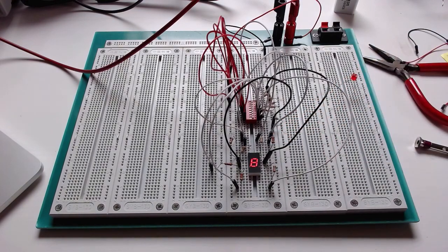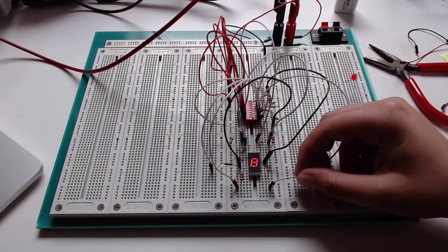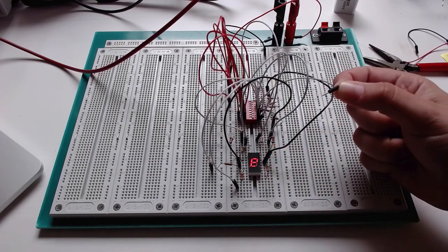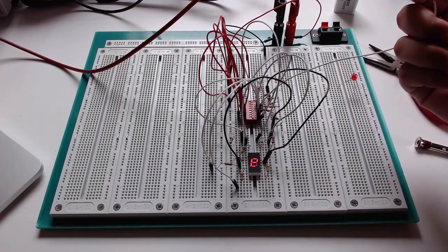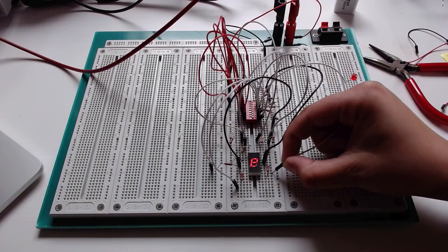This is the most commonly wired wrong thing that I see out of both digital systems and microcontroller students. Okay, so of all of the classes that I teach, of all of the subjects that I teach, the wiring of a 7-segment display is the single thing that I see done the most wrong. So I want to show you a couple of wrong things that students do so that you can avoid doing them. One of the wrong things that I see is that a student will just take the pin directly from the dip switch and connect it directly to the segment.